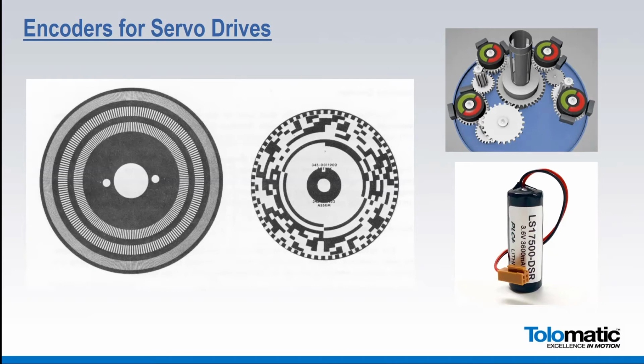And this has become quite popular now, with the improvements in battery technology, now that they last so long and are low cost for good batteries. And that does tend to be a little bit lower cost encoder system than the geared encoder system on the top there. In general, I think there's not really any performance difference between battery-backed or geared encoders for absolute encoders. But I do think that when you see battery-backed encoders, they do tend to cost a little less.